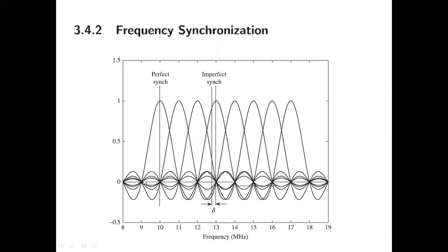What is orthogonal, by the way? Now see here, at this particular line, all these carriers have overlap with each other. You see here, this is indicating overlap. But if I choose properly at the center, at this particular point, the contribution from all the neighboring subcarriers has gone zero.